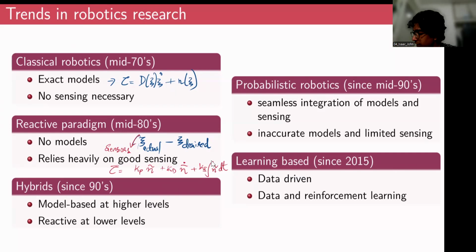For example, if you have a 2 degrees of freedom robotic arm like this, we can teach the robot that if the robot is in this configuration defined by these x and y coordinates, probably I'll define this by x1 and y1, the joint variables would be theta 2^1 and theta 1^1, where this top number, the superscript, depicts the instance, right?